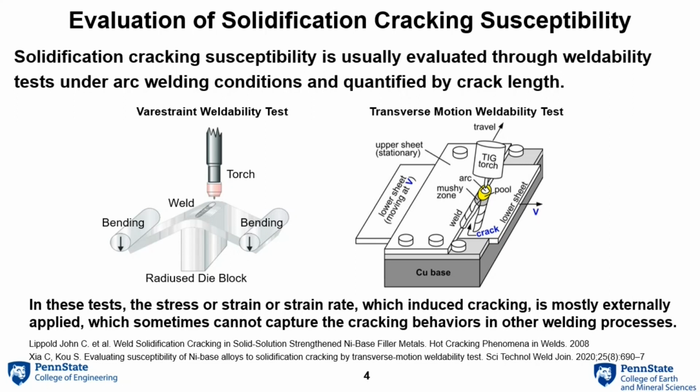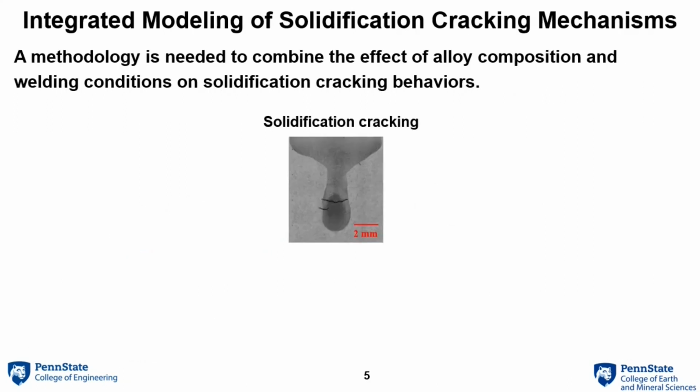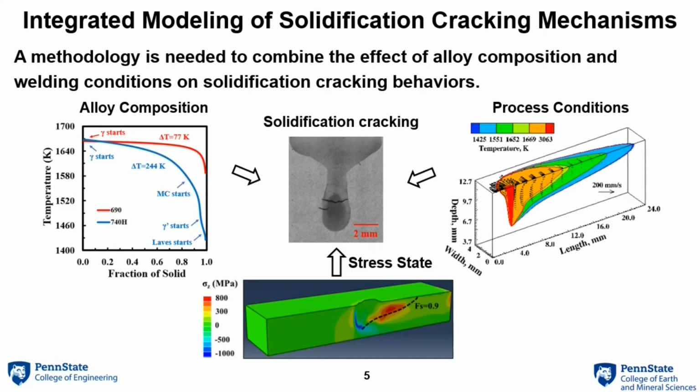We can see from these tests that the stress or strain rate which induces cracking is mostly externally applied, which sometimes cannot capture the cracking behaviors in other welding conditions, specifically the high power laser welding of thick section structures. To overcome this limitation, in this work, a new methodology has been developed which is able to combine different components of the cracking issue, such as the alloy composition, process conditions, and the stress state, to better understand the solidification cracking behaviors.